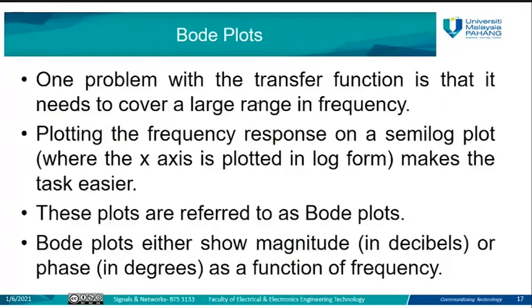So what is a Bode plot here? The Bode plot is a sketch or graph, usually used to investigate or analyze the frequency response of a system. This system, as we said, can be electrical, mechanical, whatever it is, but it has a transfer function, which relates the input and output of the system. The Bode plot is one of the frequency response methods to study the system stability.